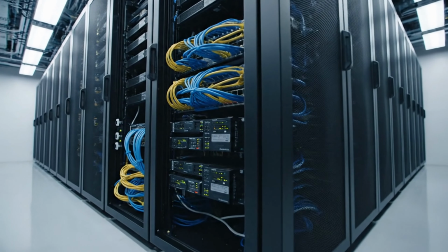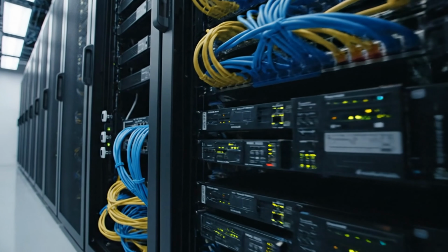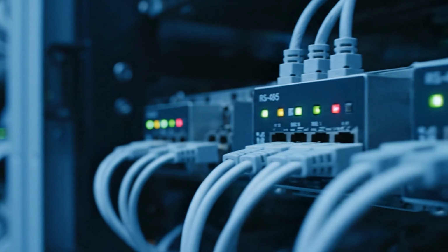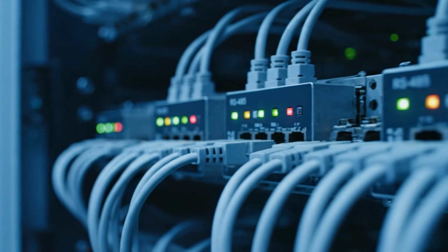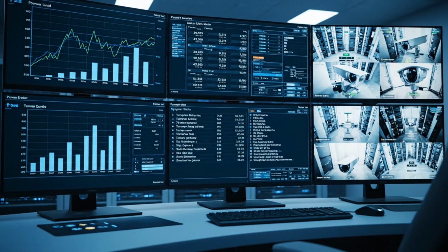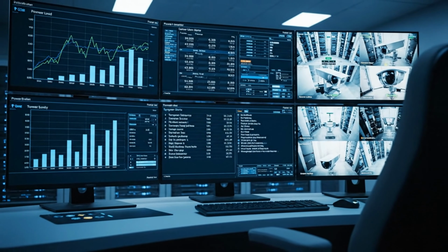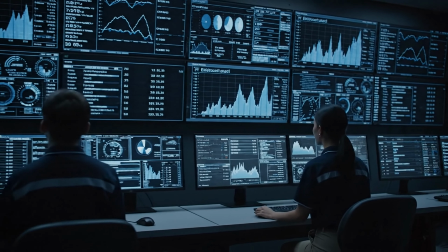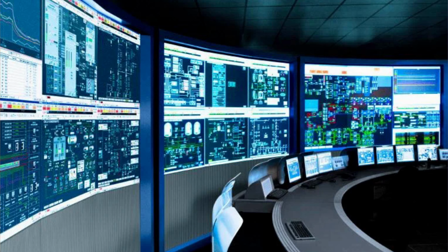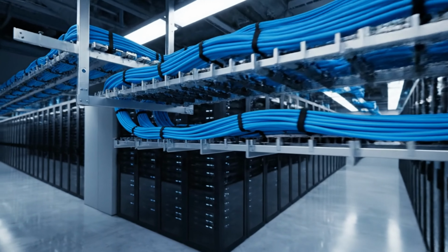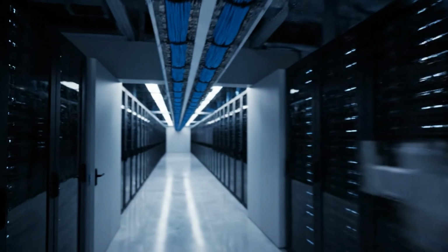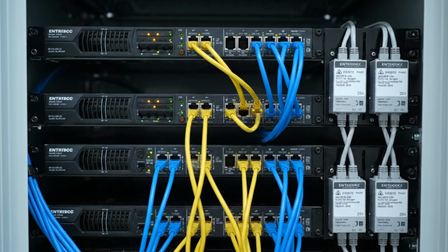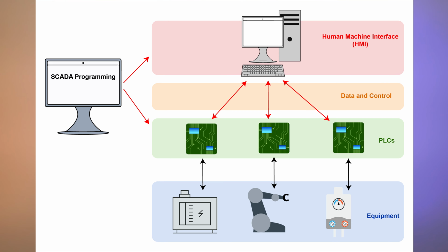Modbus TCP is just Modbus RTU running on Ethernet without routing information added. But that one difference changes everything. Instead of pulling devices one at a time over an RS-485 chain, TCP allows your monitoring software to query devices in parallel. It lets you scale across rooms and buildings. It lets you pull in thousands of data points per second without overwhelming the network. And because it's Ethernet, you get built-in long-distance capability, redundancy options, and support for remote access that would be impossible on RTU alone.